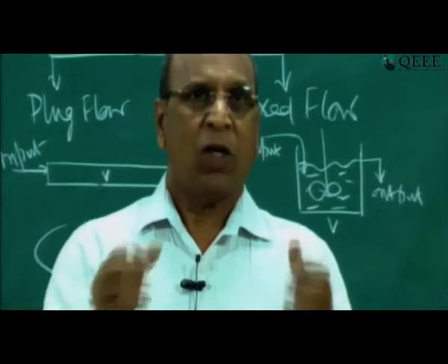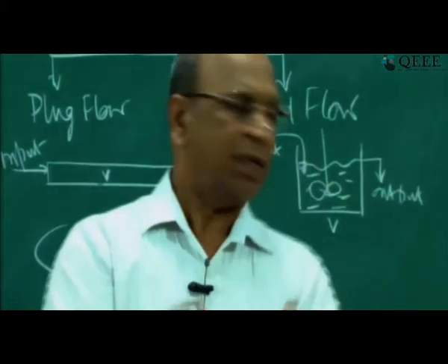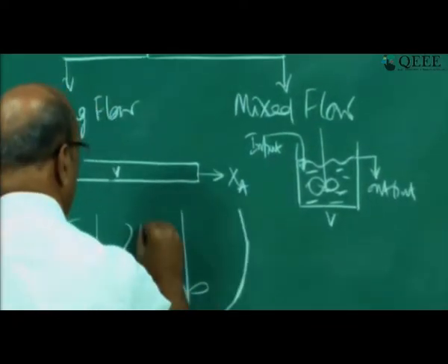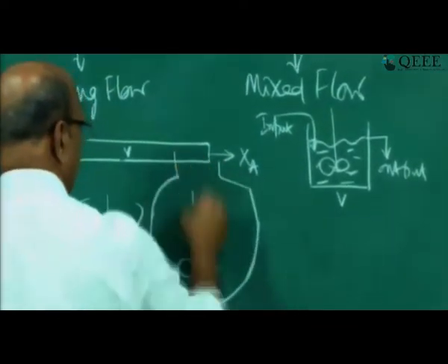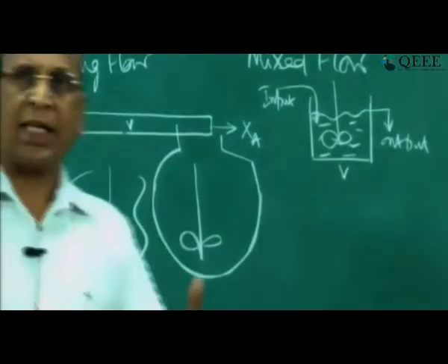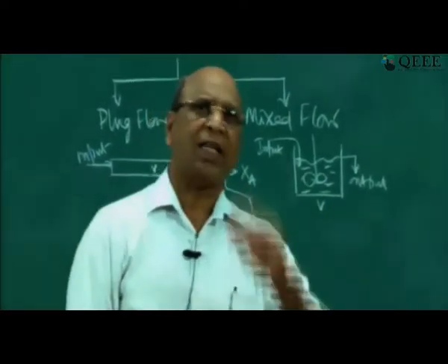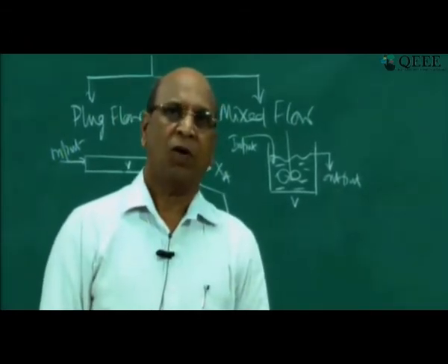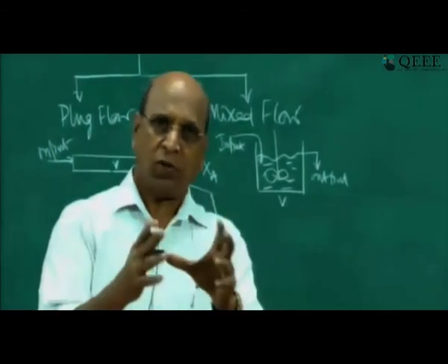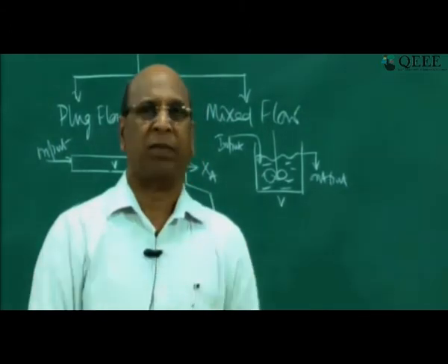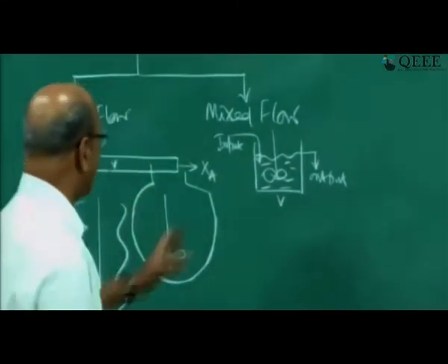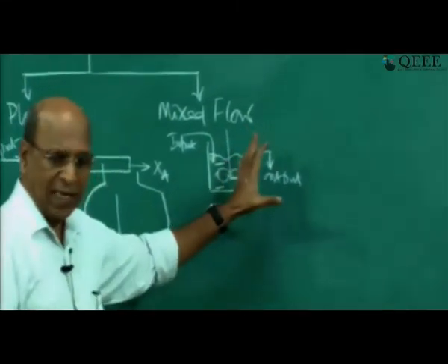You know that to make a spherical tank like this, somewhere here you will have it like this, and in industry at that large scale, it is not that easy to make these spherical tanks. For storage vessels they do if it is absolutely required. Otherwise for reactors mostly the simplest design is this kind of cylindrical tank.